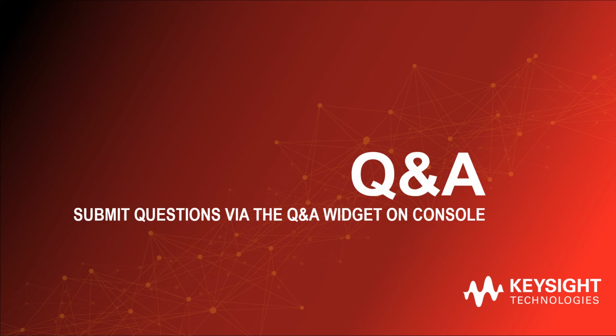The next question is, how is component testing done for 800G and beyond designs? In the development and evaluation of ultra high speed chips and optoelectronic devices, the frequency domain parameters, for example, bandwidth, gain, flatness, and so on, are the most basic parameters to indicate and measure the device performance. So before even digital signals are applied, measurement and analysis of S parameters, which are obtained with the high frequency vector network analyzer, can give a good indication of component performance.